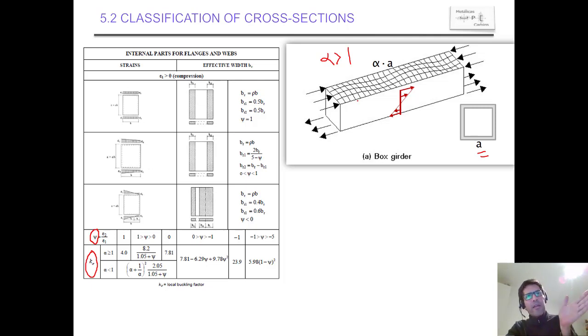Let's say it is welded to a column on one side and perhaps to a column on the other side. So the flange is supported by one web, another web, one column, another column. It's simply supported on all four sides. So this is the table we need to use for those cases: a plate which is simply supported on all sides, and fully compressed on one side.